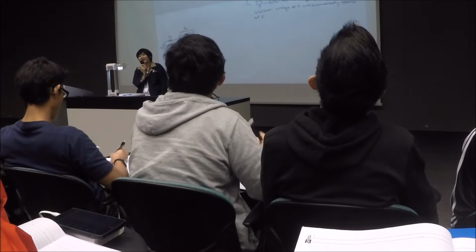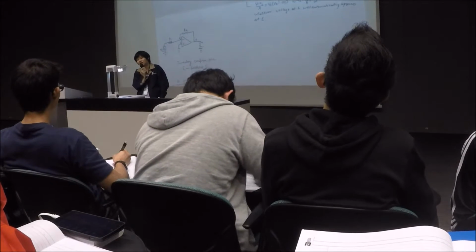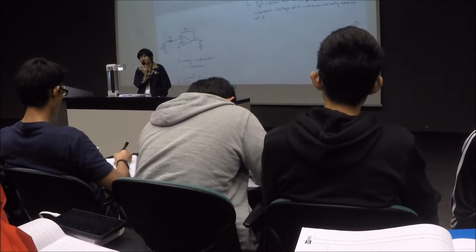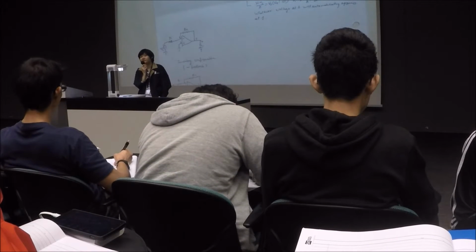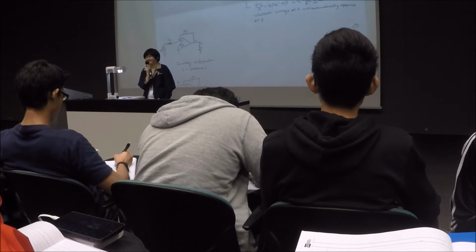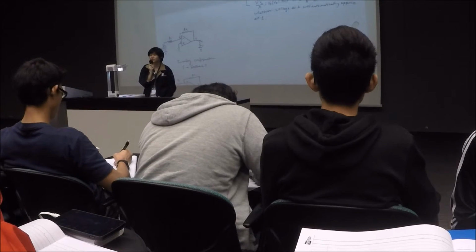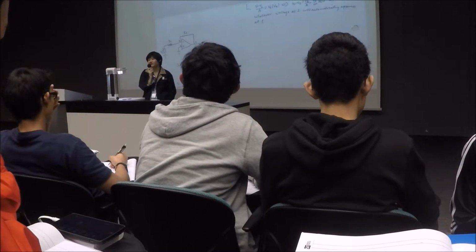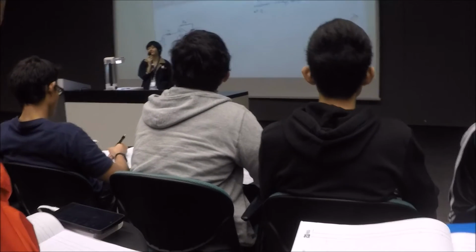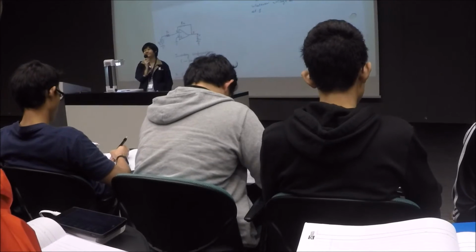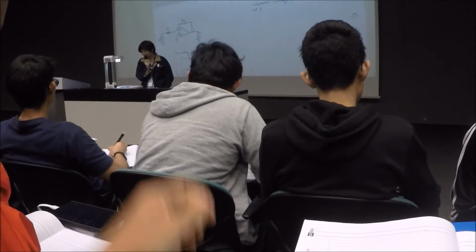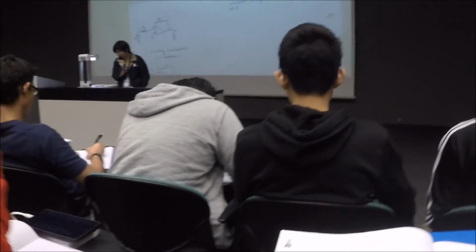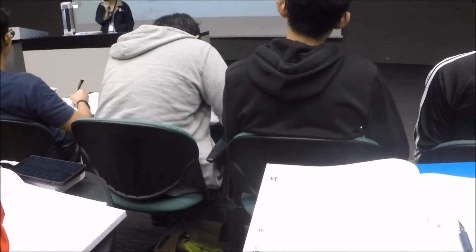And if you supply the input from the negative terminal, your output just has a different sign, minus V1. So it actually has 90 degrees phase difference. Sorry, 180 degrees phase difference. So we call it inverting configuration.